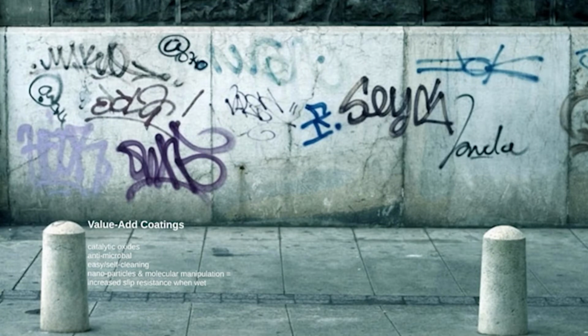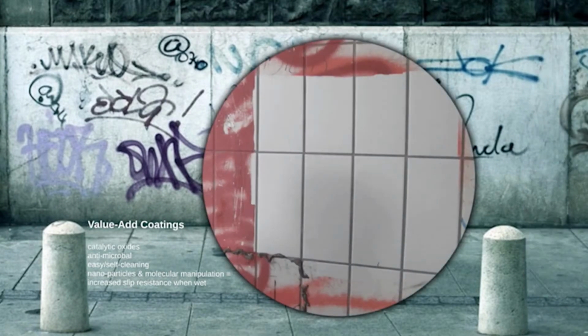Now, this is a huge thing for us in the design professional world, the value-added coatings that we're adding to our glazes and the bodies of our tile. There's all sorts of amazing technology that we can do today, from tile that's more slip resistant when it's wet, to tile that has catalytic oxides encapsulated within the glaze that make the surface actually resist paint and other contaminants, but also destroy organic material and bacteria and viruses upon contact with the surface.